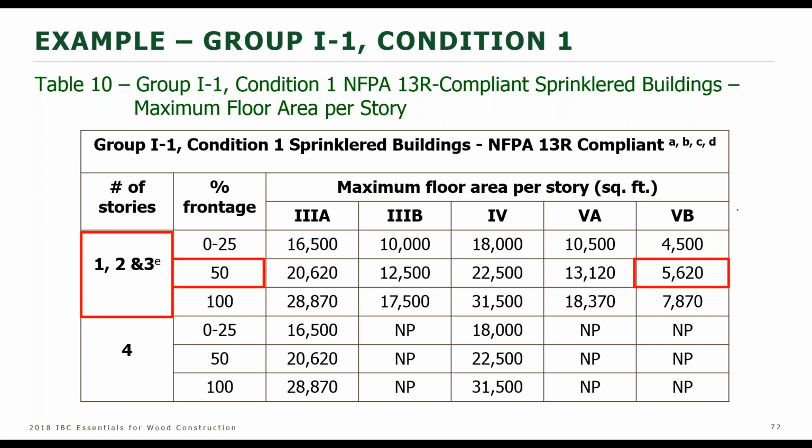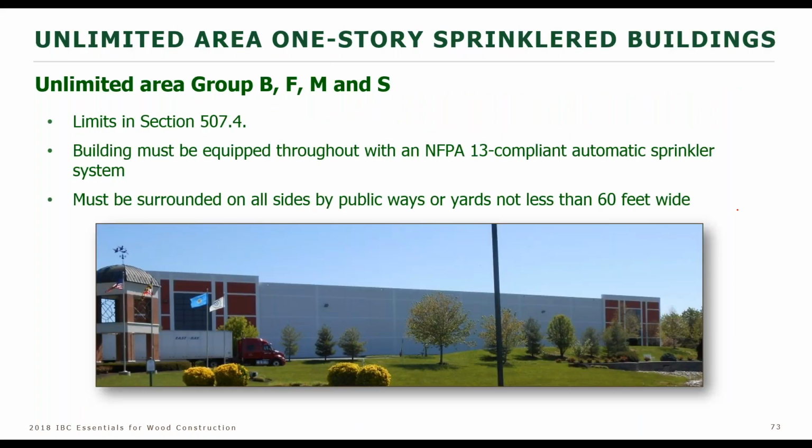So this is a great feature of the Code Conforming Wood Design. And that alone may be a reason to keep it on your desk. Many people don't know that there are unlimited area wood frame buildings permitted. The key here is single story and sprinklered. These use groups, single story, sprinklered, and 60 feet around the building, fire separation distance, unlimited in area. Many people are surprised by that.